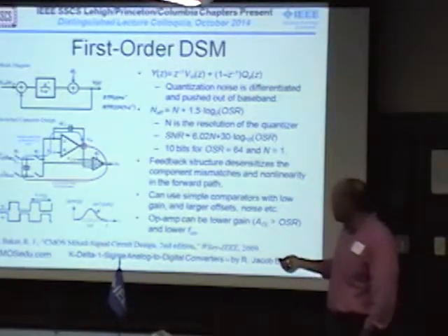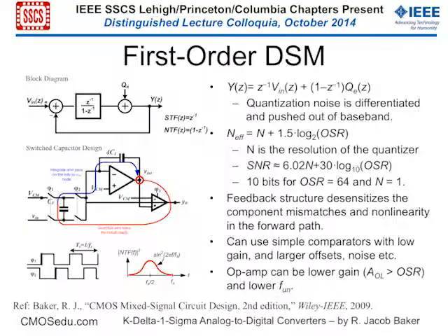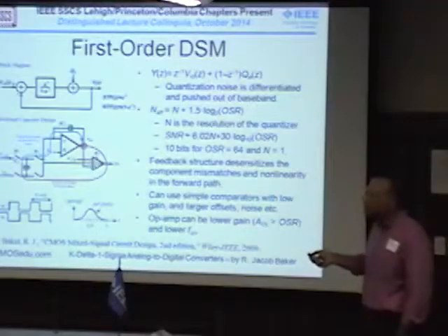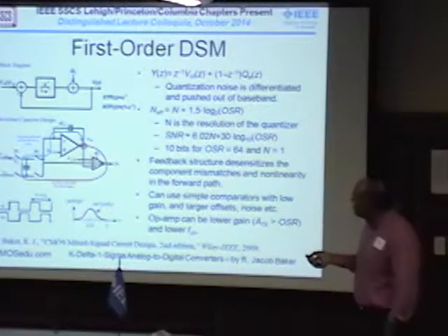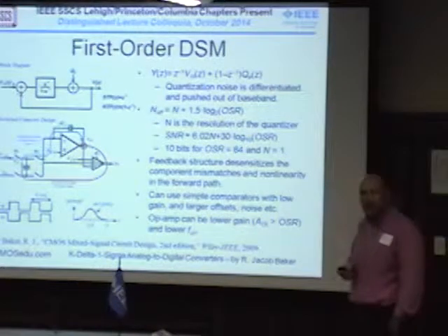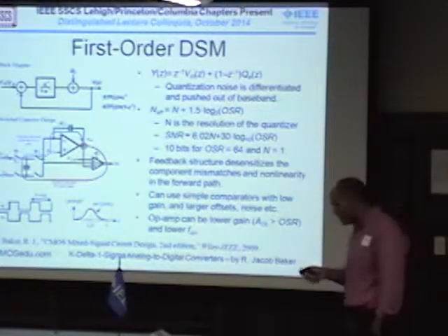And it basically boils down to that the forward path in a feedback system is much less critical than the feedback path for setting the performance in the gain. So if I use an op-amp with 2,000 gain versus 1,000, I got a gain of 10 op-amp, it's not going to vary very much because the feedback sets the gain. So the key point here is that having precision in the forward path is not even remotely as important as having precision in the feedback path. And that's what we're going to exploit here, okay?